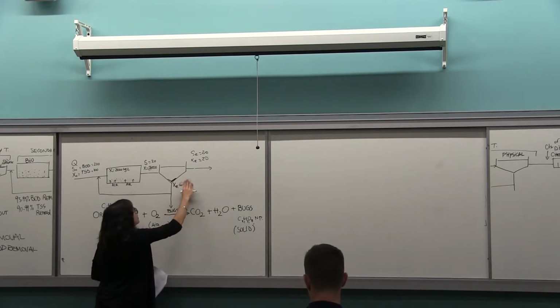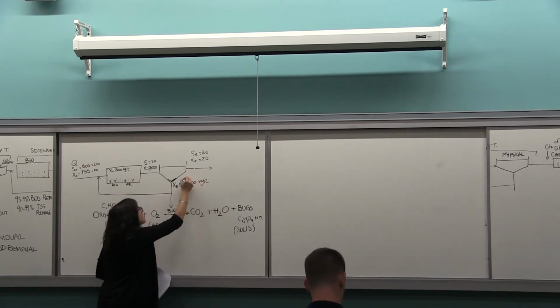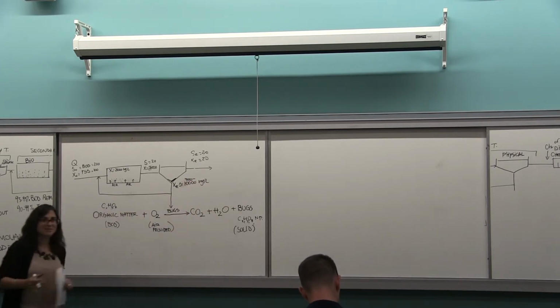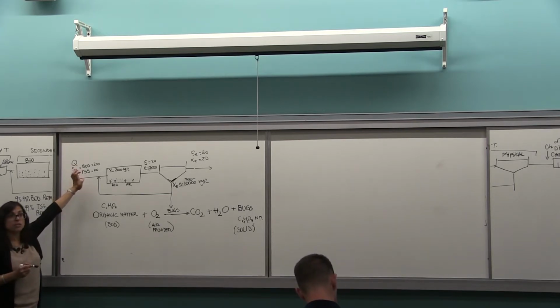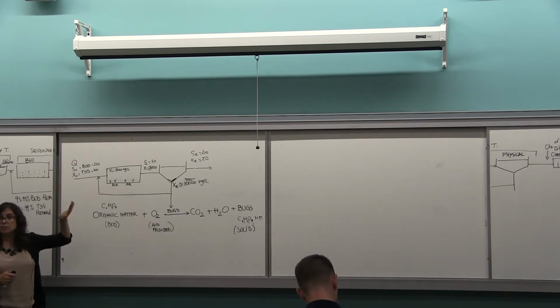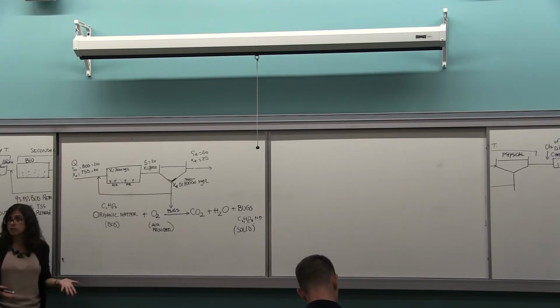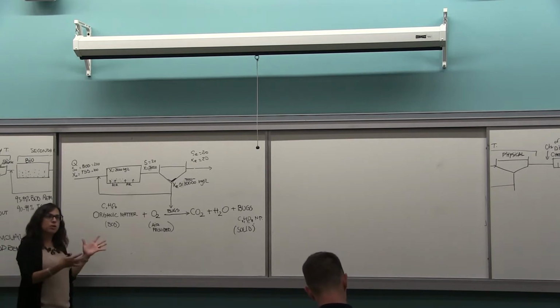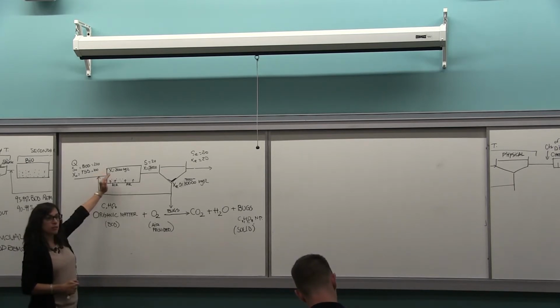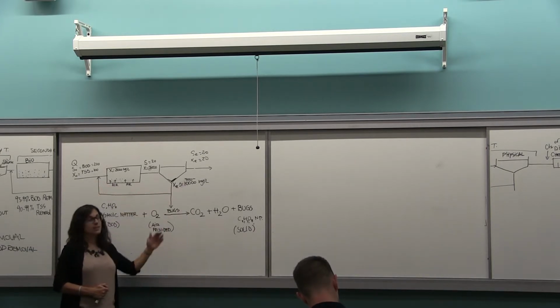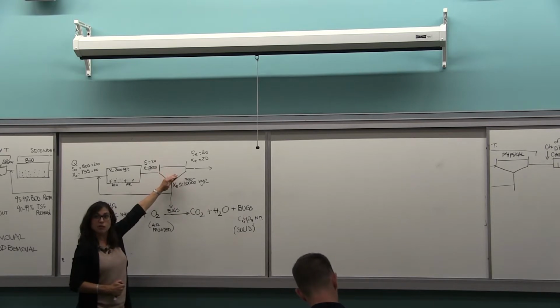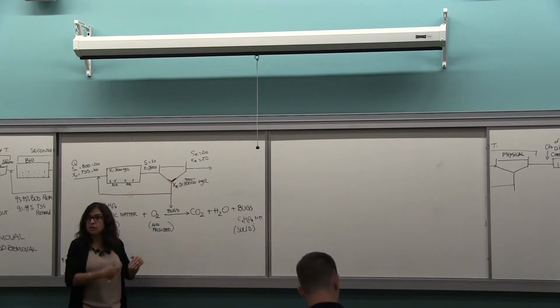Usually 7,000 to 10,000. So what we are trying to do is transform these BODs, this organic matter that if released into the environment will consume oxygen, producing anaerobic condition in the river, from soluble, using bugs, into new bugs that are solid. And then we send everything to a clarifier that will settle out the solids.